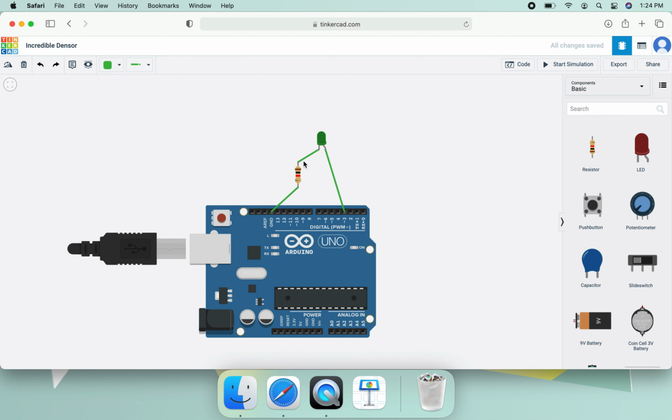Now after this, you can also add nodes in your circuit. Like here I'm using a 1 milli ohm resistor and there are chances that I can forget it. Then I can add nodes here, which is available with this option. You can just click on this one and you will find nodes here. You can put it anywhere you want. Like I want to put this with this resistor. And then you can add any text here like 1 milli ohm resistor.